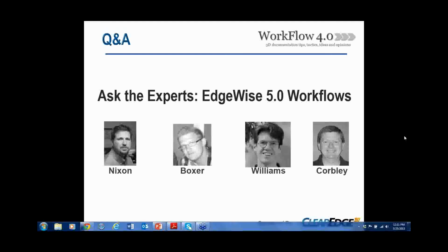All right. Okay, let's see. Kevin, again for you, does the new pipe extraction feature negatively affect pipe fitting when there are limited scan points to work with, like above ceiling scans or pipes that are high overhead? No, it's better than it used to be. So you're going to get better quality results. Even with low point count, you may not get an extraction if you have too few points, but it's going to be at least as good as the old version, and in most cases better.